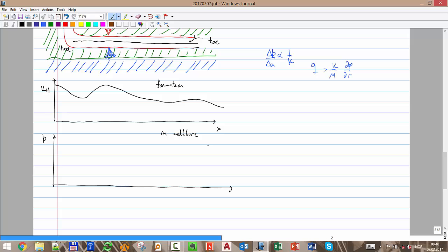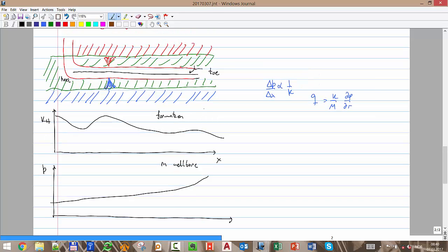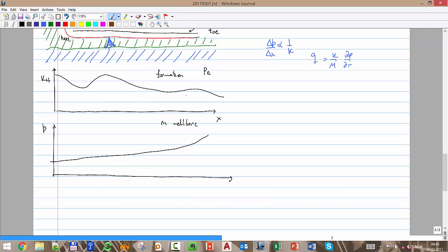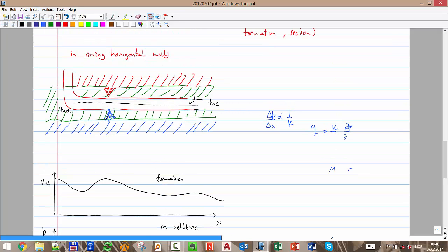It should look higher here. To have flow, you have to have higher pressure and low pressure at the end, right? So again, if I have here the same reservoir pressure, no, let me make some space. If I assume that I have the same reservoir pressure along the wellbore, then the driving force of the rate is going to be P minus this P, in each position inside the wellbore, that pressure difference.